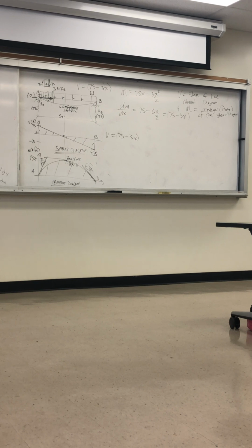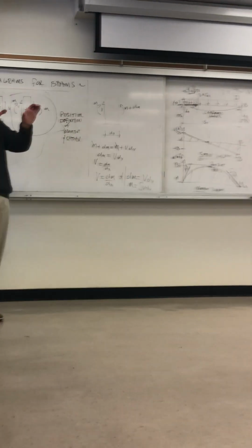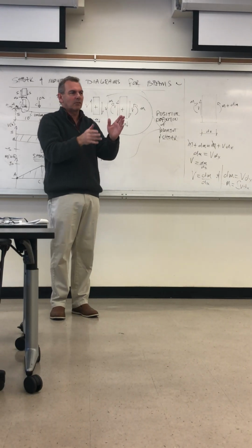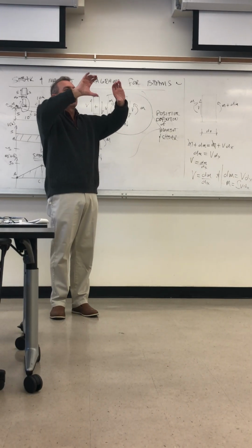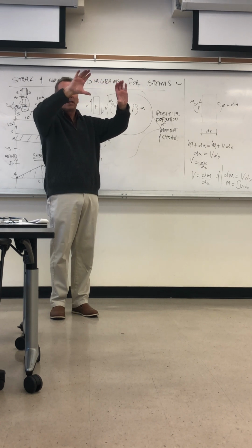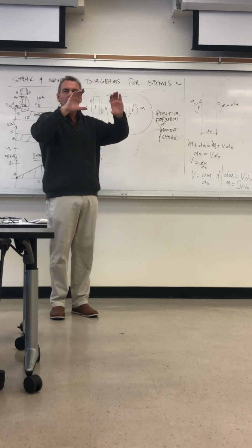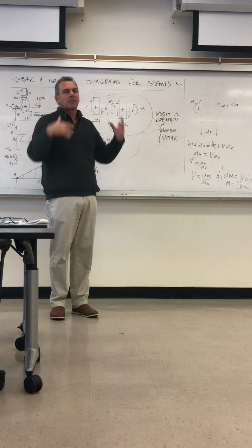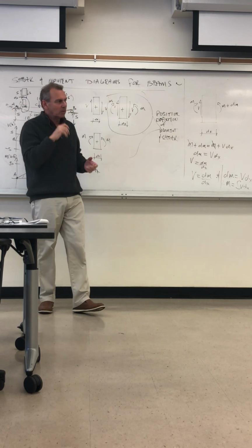Moment is if you grab something and you bend it this way or this way. If you bend it this way, it's called positive. If you bend it this way, it's negative. And it sets up flexural stresses that change over that whole cross section. So imagine you grab something and do this. You can imagine the fibers that are getting longer on the top and shorter on the bottom. And so this is the expression there, it's Mc over I.